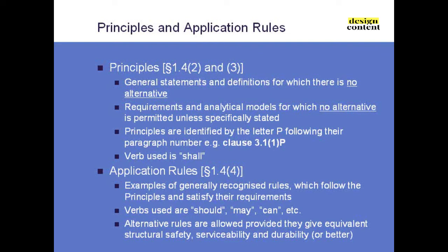In theory, you can do alternatives to the application rules if, basically quoting from Eurocode Naught, what you do provides equivalent structural safety, serviceability and durability or better. Clearly that would be almost impossible to prove. I wouldn't want to be demonstrating or trying to prove that to an expert witness. I'm sure you could, but it would be best not.